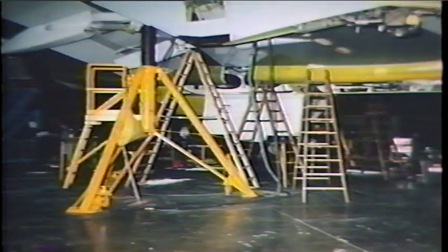All door installation and adjustments must be done only when the airplane is on its landing gear. No rigging can be done with the airplane supported on jacks. To prepare for rigging, configure the aircraft as outlined in the maintenance manual.